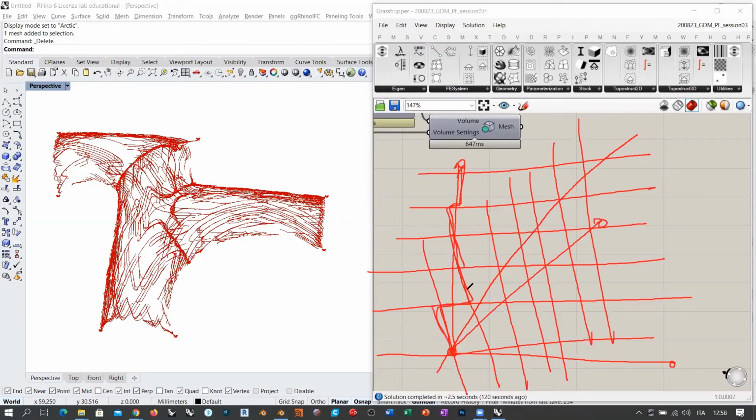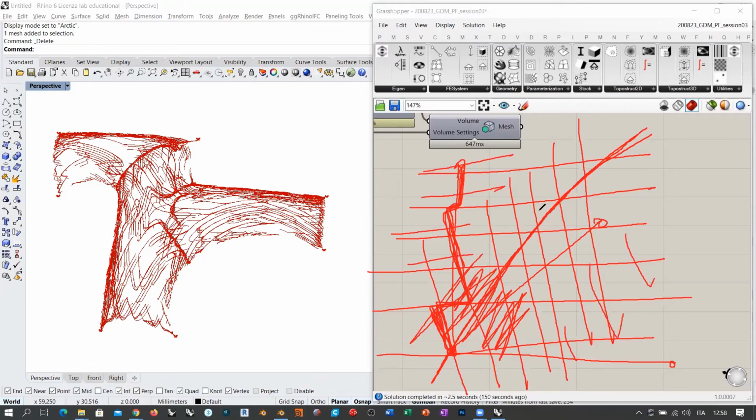Now, if I give this path here a unique thickness, I will have the same thickness at each level of this fiber. But the stressed part of the surface is more sticking to the stress lines. So I need more resistance close to the stress line and less resistance far from the stress line, right? So what if I give these fibers a variable thickness, which is thicker when they are close to the stress line and thinner when they move away from the stress line? Okay, so this is my goal actually.